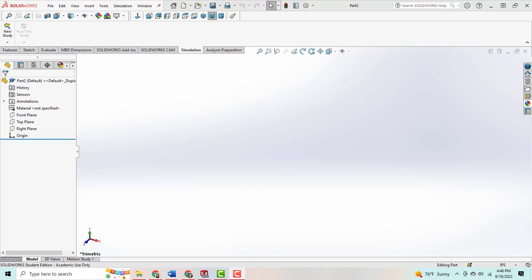For this milestone, we're going to practice some of our extrudes, shells, using sketch and convert entity features, patterns, adding in global variables and applying those equations so we get that parametric modeling. And then, once we're done with this Skinnybrick, we will move to creating configurations and 3 derived parts. I will have separate videos for those 2 sections. So right now, this video is going to cover just creating that Skinnybrick file.